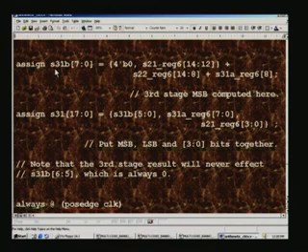This one, S31B is put here. Once again these 2 bits 6 and 7 will be zeros, so we are not using that, therefore 5 to 0 we are optimizing by hand right here. And then what we are doing is we put together the MSB results and the LSB results, and then what we have here is the concatenation of 3 through 0, the 4 bits we had not used earlier for S21, and that is what we are concatenating here.